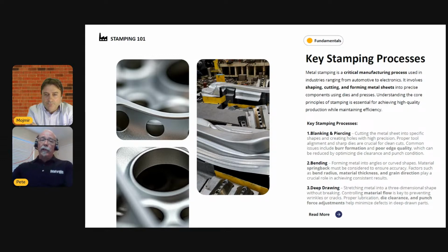When we talk about punch and die, I don't know how well this shows up on the screen, but I have a die matrix and I have a punch. The way that this punch fits into the die matrix must be precisely aligned. The punch cannot enter on an exaggerated angle. It must be exactly perpendicular. And the die could be properly aligned when we have it in the die shop, but when we put it in the press, we may experience some misalignment.